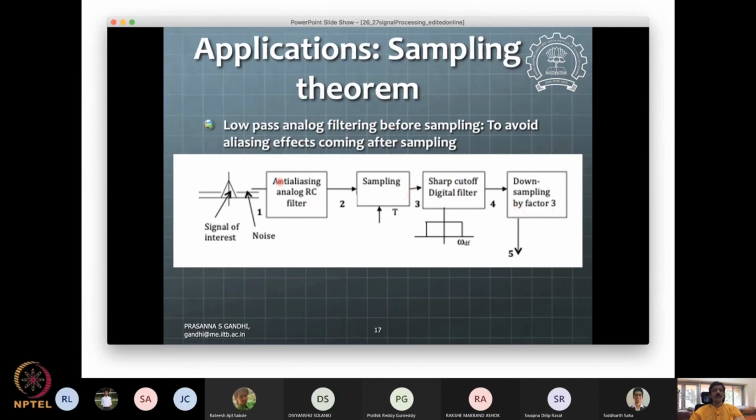You do just an analog filter and then sample at a high sampling frequency, and you'll be good to go. Or you may say, I need to remove some parts of the samples so that I can have a better processing possibility with downsampling. Then you do these additional steps and reduce your number of computations. So this is one example of how you start thinking about sampling and use it in a typical mechatronics domain application.